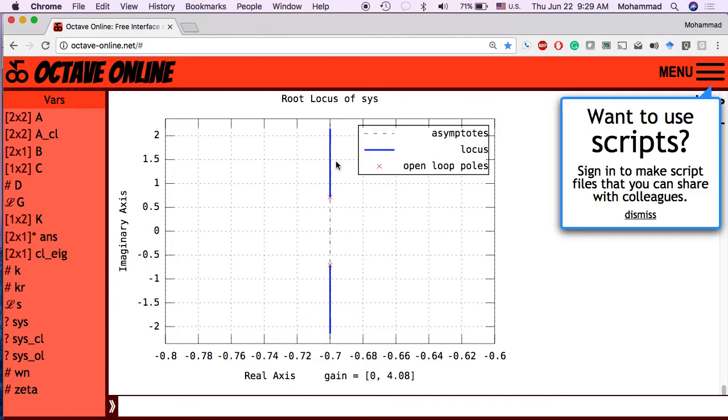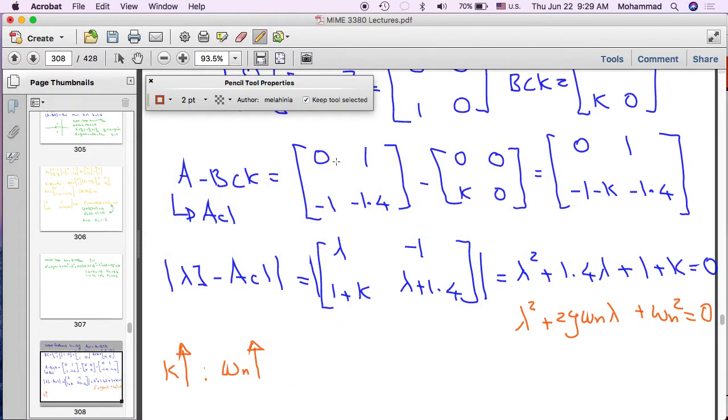But what is happening to the damping ratio? It appears from the equation that it stays the same. But move on this blue curve as you go up, and the damping ratio definitely goes down. The angle with the imaginary axis goes down. On the surface, it may appear that your damping ratio doesn't change, but let me write it down and justify what I mean. Omega n goes up, but damping ratio goes down.